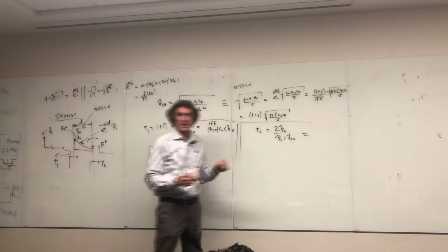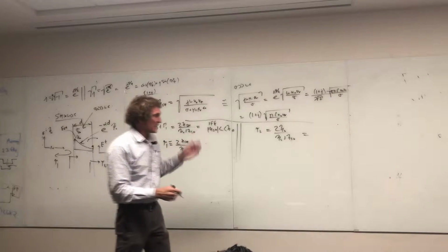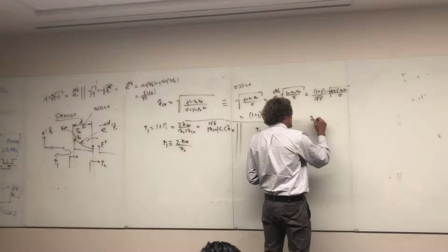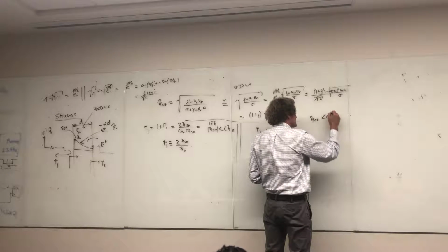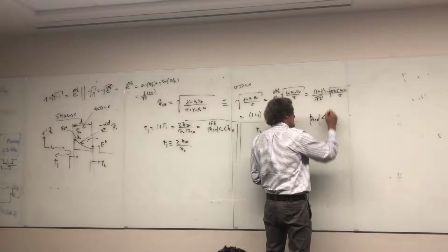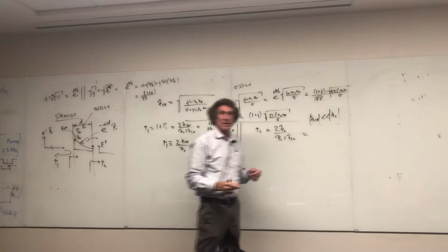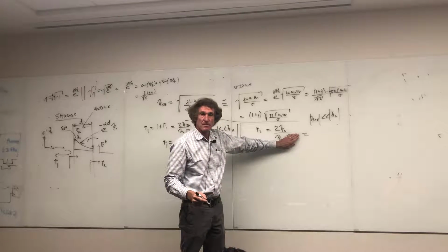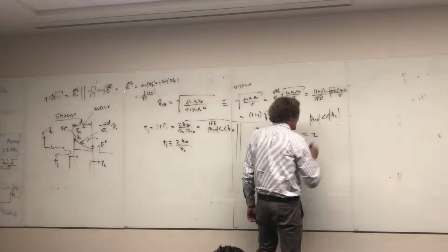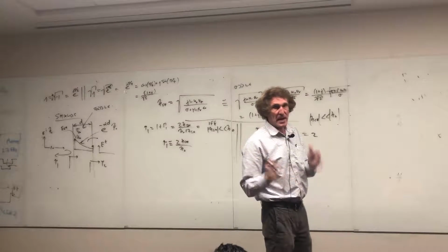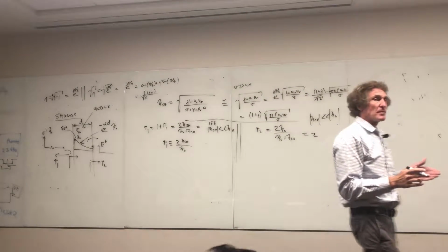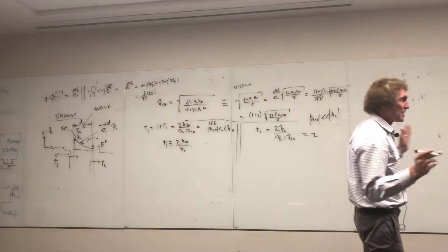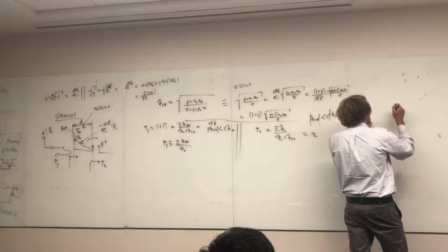Now, look at that for a second, and you can see that if we make the assumption that the magnitude of eta shield is much less than eta naught, then what happens to this number? You cover up the shield, you get 2, don't you? Sure, you get 2. So that means the magnitude of the transmitted field, and never worry about phase when you're dealing with shielding effectiveness or shielding. They don't care about that.